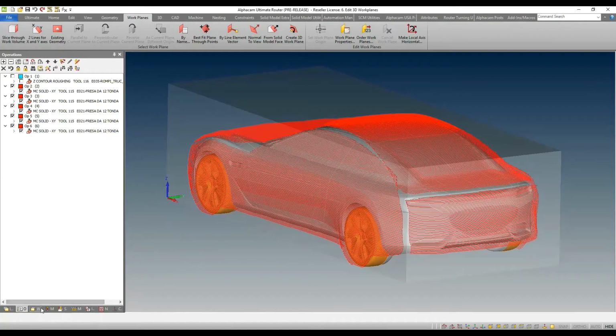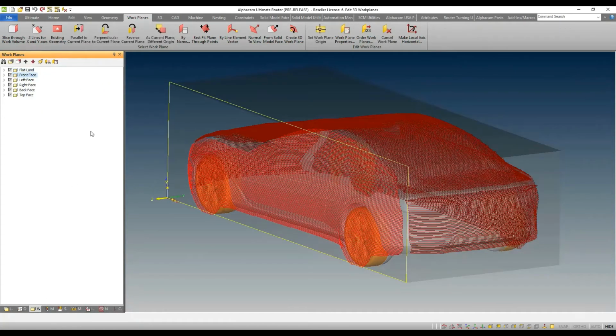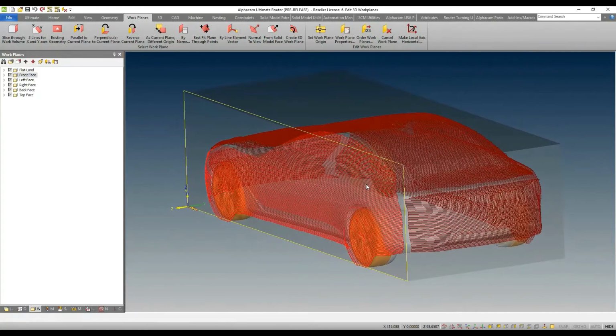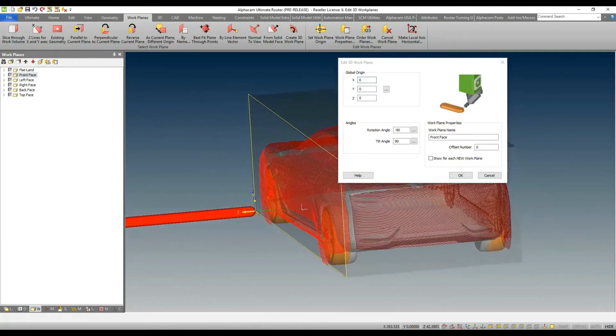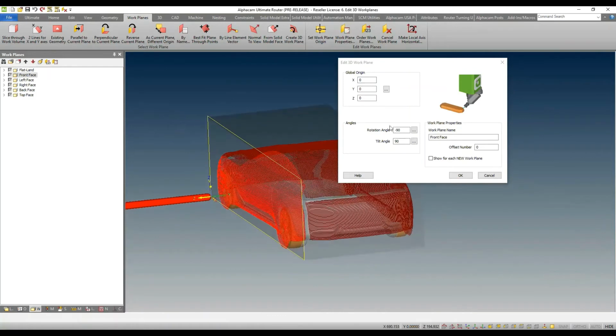A practical example is this. Let's say that for whatever reason, you want to modify all of those toolpaths included in that plane by moving the origin of the plane just a small amount. This is a situation that arises, unfortunately, sometimes when the TCP calculation point on machines is not correct, or, for example, if the length of the tool hasn't been measured correctly at the machine. This will allow me to right click and edit. And as I was mentioning to you, we can make small changes to account for those little tiny discrepancies.